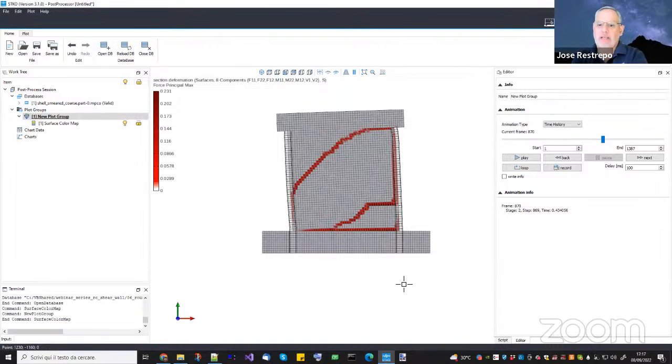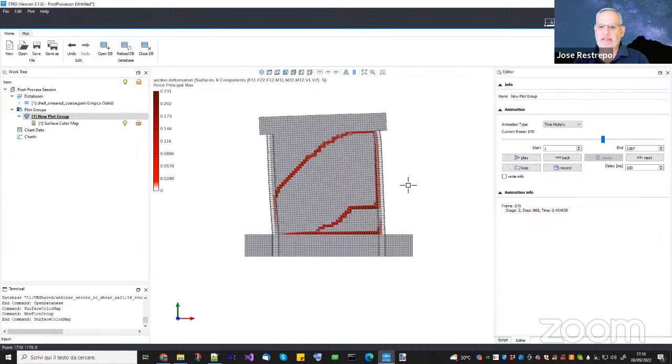No, it's mainly related to the state of the stresses. So before the structure cracks, also, because we are not rotating anything, you better start with a good idea where the cracks should begin to develop, and an idea is that you could eventually start with a linear finite element analysis.